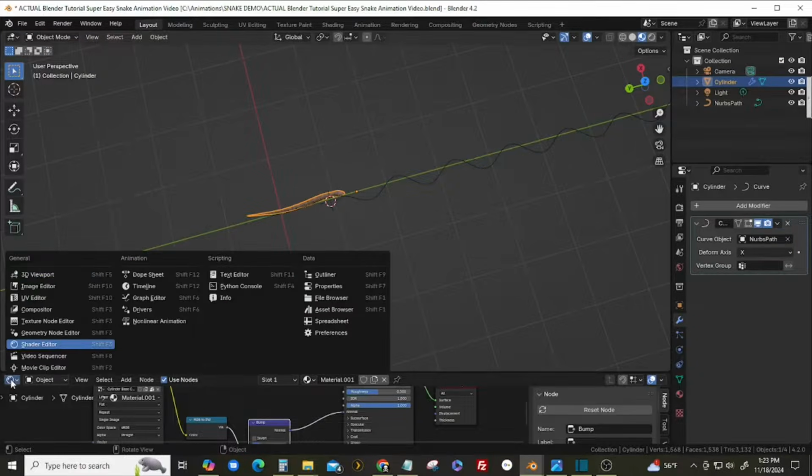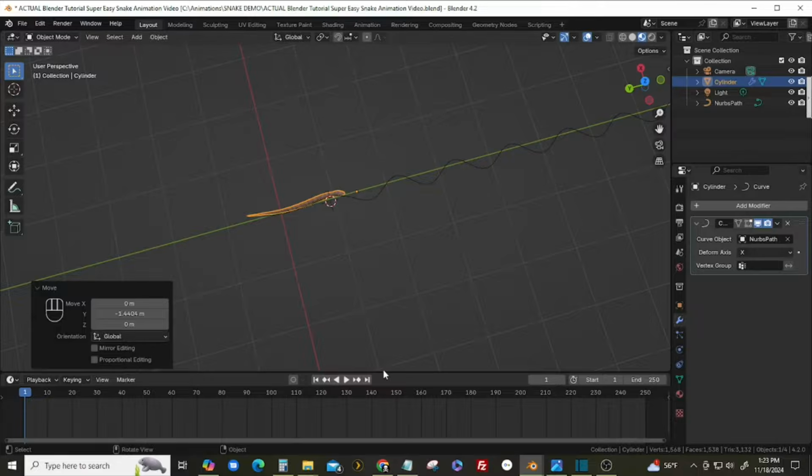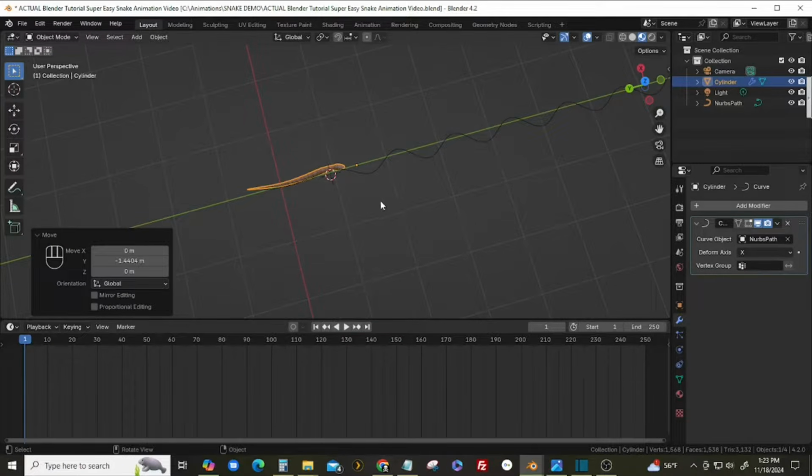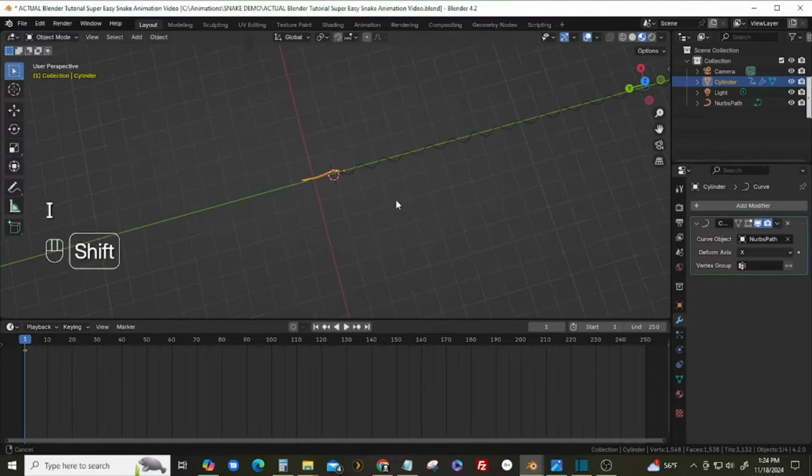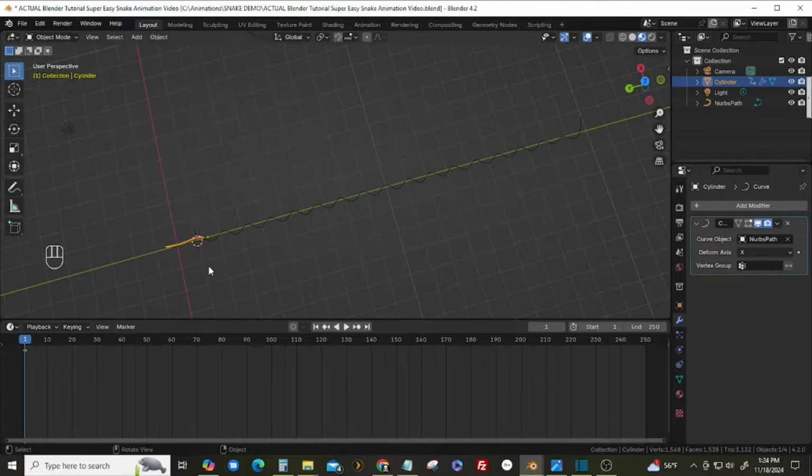So we'll switch to the timeline down here on the lower window. And what we're going to do is start at the first frame, 1. If yours isn't there, you can click here to move it in that direction. And to start animating this, all we want to do is insert a keyframe, and that keyframe is going to load down here in the timeline. You'll see it. You'll hit I to enter that first keyframe, and we'll hit GY.